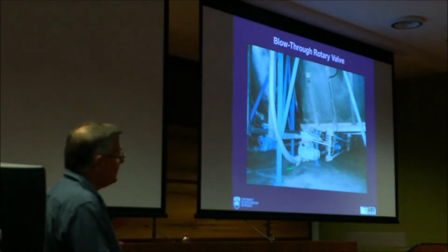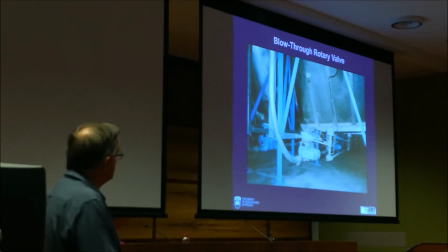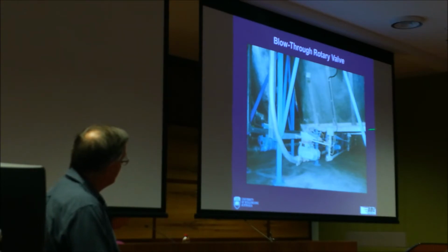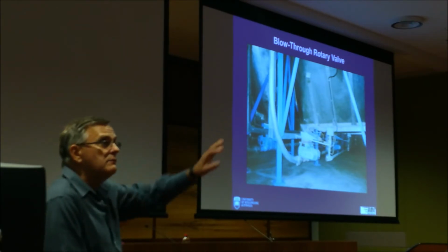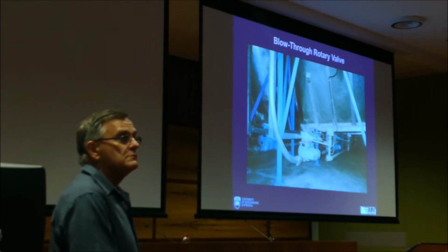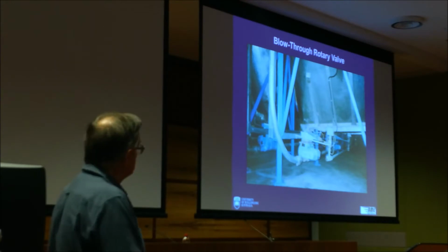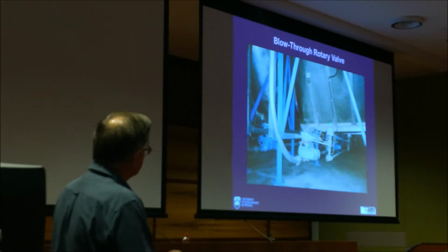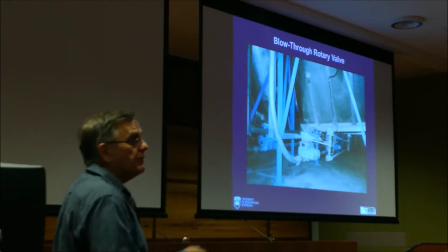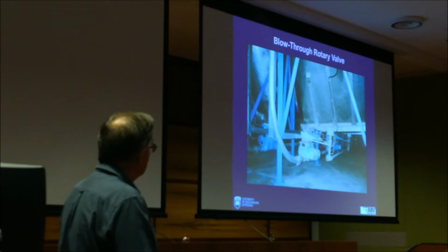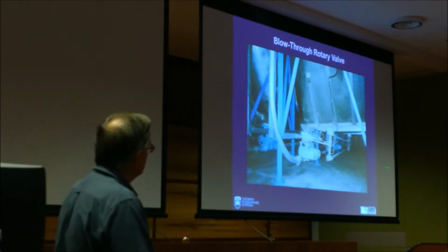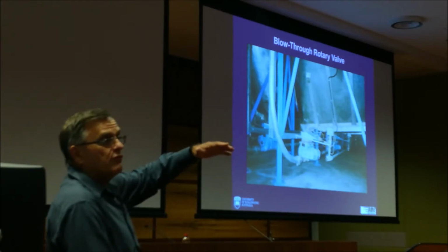In this case, this is a milk powder factory, and we've got a number of fluidized bottom silos here. One there, 2, 3, 4, 5, 6, a whole bank of them. And you've got all these little blow-through rotary valves connected to the one pipeline. You only feed one at a time. So this one's feeding, the powder's coming through here, dropping down, flowing through here to another silo or whatever. And then we stop that one, then we go to the next one, blow that one through. Okay, then you go to the next one. The other advantage of blow-through is low headroom.